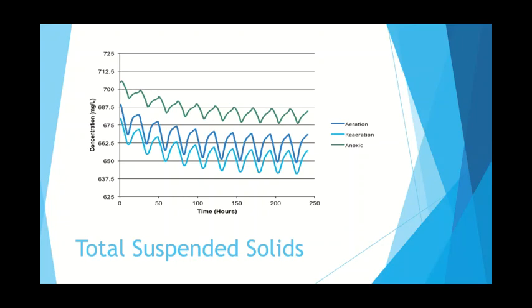The suspended solids are important since they represent the bacteria needed for the chemical reactions within the 5-stage biological process. The suspended solids should be between 2,600 and 3,600 milligrams per liter. The concentration should not exceed the plant capacity, which is 4,000 milligrams per liter.